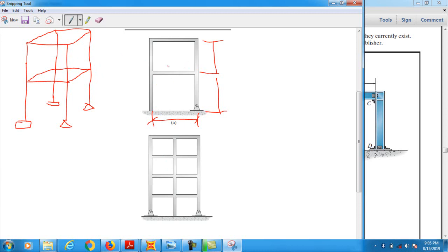The modeling of this 2D frame is simple. You just select the 2D frame template, and in that you insert the number of stories as 2, the story height you can assume, the number of bays as only 1, and the bay width you can assume, and just click OK. So this will be drawn.